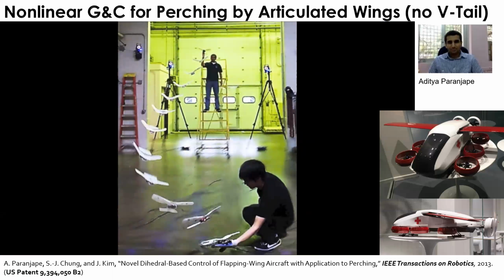You can see that compared to the conventional PID controller, it lands much more smoothly, and it can get closer to the ground. Again, this is called the Neural Lander, where we use a spectral normalized deep neural network combined with a nonlinear controller to improve the tracking control performance. Another example is scanning the ground closely. Then you can see that you have a much smaller tracking error, as opposed to conventional PD or PID control.